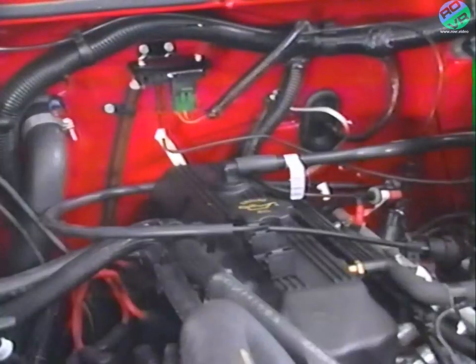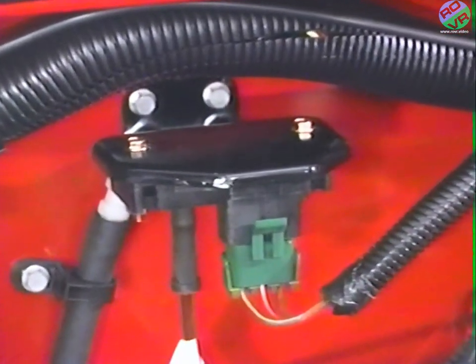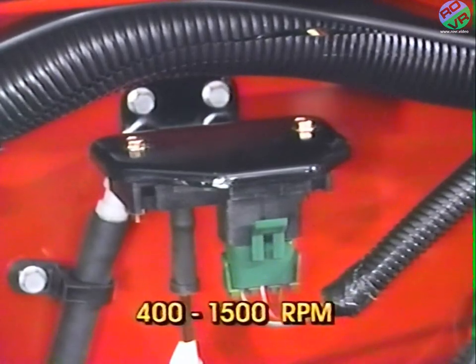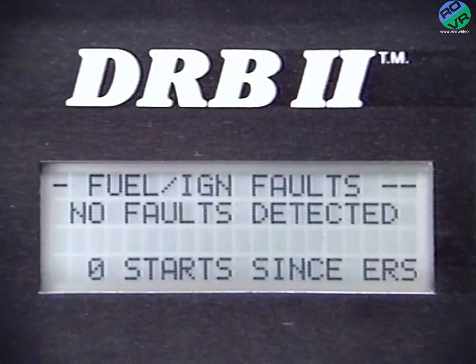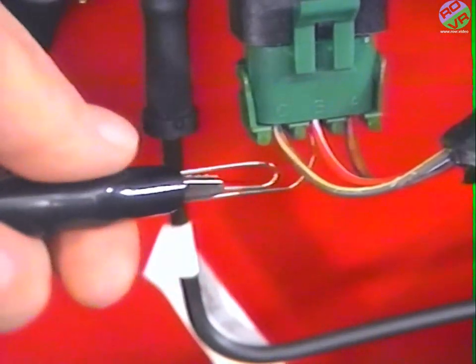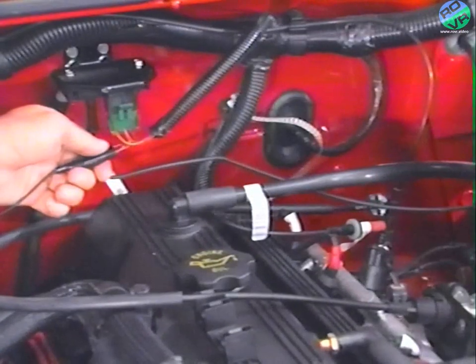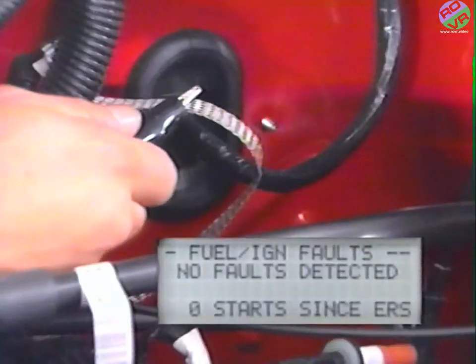As an example, let's look at the MAP sensor circuit. Now let's assume that one of the arming conditions or fault criteria for the MAP sensor circuit is that the engine must be operating between 400 and 1500 RPM to be monitored for a fault. First, we check for fault messages and find that the DRBII screen reads no faults. We'll simulate a fault by taking a jumper wire and back probing the MAP sensor at the output wire. Then we'll start the car and raise the engine speed above 1500 RPM so that we'll be outside the arming conditions for the MAP sensor electrical fault.